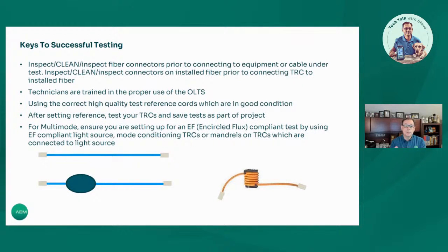Some other keys to successful testing. I've mentioned cleaning before, and this is number 1 on the list. Inspect, clean, inspect. Make sure the technicians are trained on how to use it. Again, I talked about training. Use the correct high-quality test reference cords, which are in good condition. So correct reference cord is key.